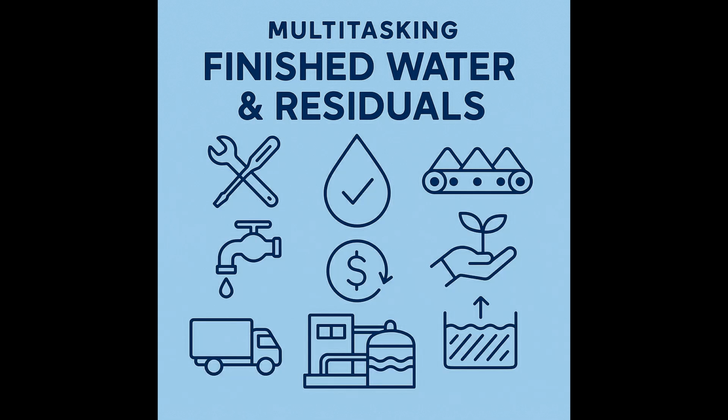Oh yeah, another major residual source. When those filters get dirty, they have to be cleaned. That cleaning process is called backwashing. So you get filter backwash water, which is full of the solids rinsed off the filters. There's also usually a filter-to-waste step right after backwashing. Okay, so more dirty water.